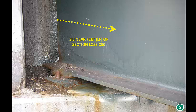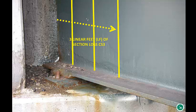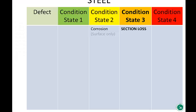So that means you're taking, from the end in this case, a vertical linear foot, and that linear foot includes the web and the flanges, each vertical foot. So if you have, in this three-dimensional slice of your web-flange combination, any section loss, start with condition state 3. That's usually where it will reside. This is state 3. And something where there's not loss, but there is surface corrosion, that's going to be condition state 2. That's how it scatters to the fair side.